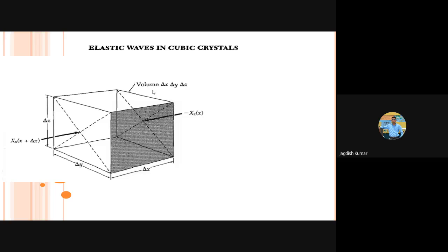We are using these Cij's as simple numbers, coming from microscopic details of the crystal, but we don't bother about how they come. We only keep in mind that our crystal has simple cubic symmetry, and because of that you will have a limited number of Cij's. That's all that comes from the microscopic information.